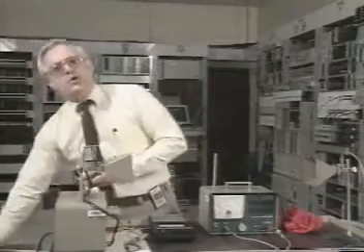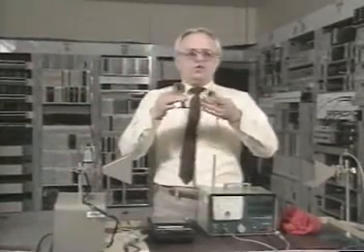I have a couple pieces of waveguide here. Rectangular tubes in this case, highly polished inside, and the size is designed to match the transmitted frequency. So as the frequencies change, the waveguide is expected to change. This is designed to make a turn, and that curve is designed also to the frequency we're transmitting.